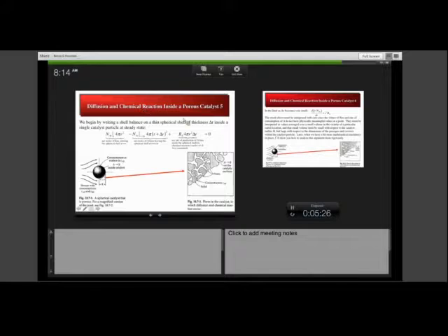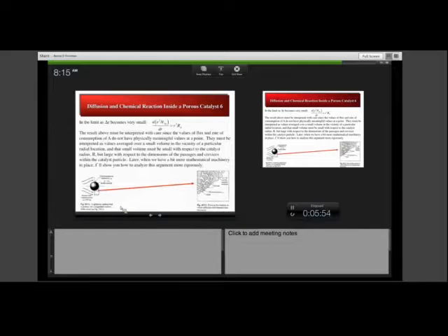And we can write that the net number of moles of A that enter at position R minus those that leave at position R plus dr has to be essentially equal to the amount of A that is produced or consumed by chemical reaction. And in this case, we're consuming A, and so this last term will be negative. So essentially, the only way that you change the flux of A flowing between R and R plus dr is if A is consumed by chemical reaction inside that volume element.